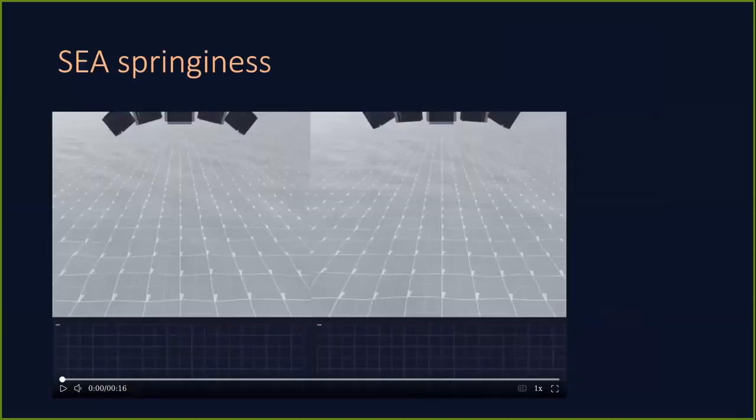So yes, we use series elastic actuators, and I thought I would demonstrate to you what this means. Here I have a video of 2 example dummy robots. One on the left, which has quite stiff springs, and one on the right, which has more compliant springs. They are dropped to the ground, and on the bottom here, you can see the Y position of the height of the core module in the dummy robots. I'll just play the video. I think that's more intuitive.